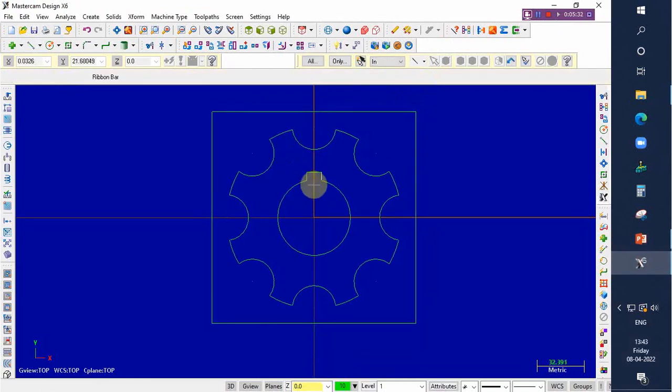And now we are going to plot 2 points. One point is called a thread point and another one is called a cut point. Through the thread point, the wire of the Wirecut EDM cutter, the tool, which is nothing but a brass wire of diameter 0.2, is entering into the profile, and then the tool has to come out via one more hole, that is called a cut point. Those 2 points we are going to create now.